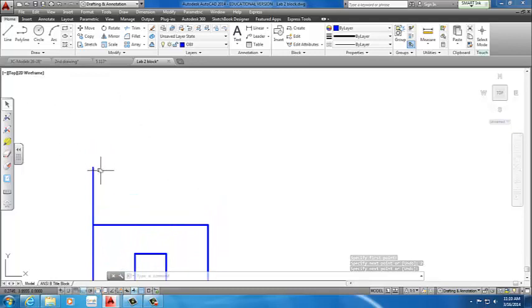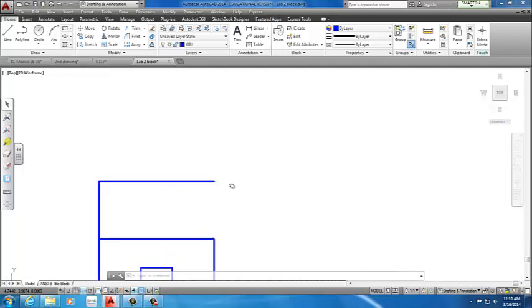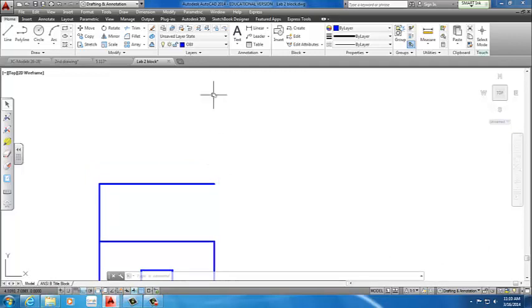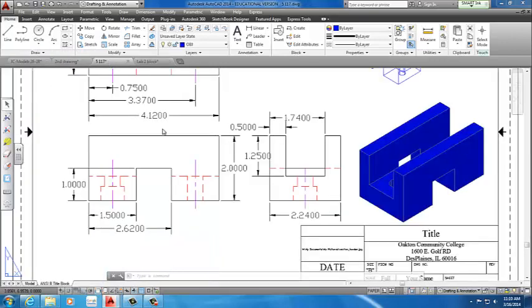And from that one point, I'm going to start drawing the top view, which should be a circle, and a box that is 4.12 across. If you don't have that on, again, right-click on OSNAP, make sure your center is active, and if that is active, we have the 4.12, and we're going to give it the full depth, or you won't be able to snap it to the center of the circle. We specify on the top view of the drawing.